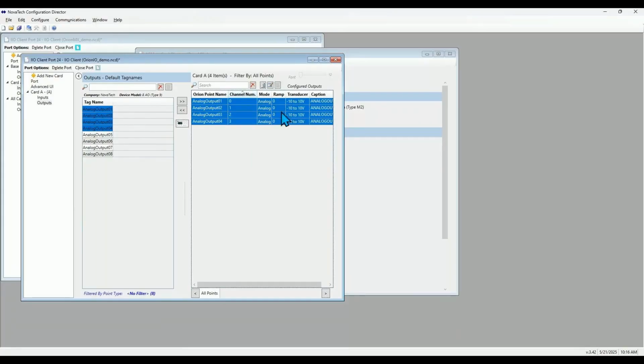Of course, you have this group of settings with the transducer. Also, something you may not be used to seeing is this option here that is ramp. Now, what ramp does, ramp dictates an amount of time that it's going to take if you have an output value set on here. And if you enter a different value and you force that control, the ramp time indicates the time it'll take for that new value to be ramped up to or ramped down to from the old value.